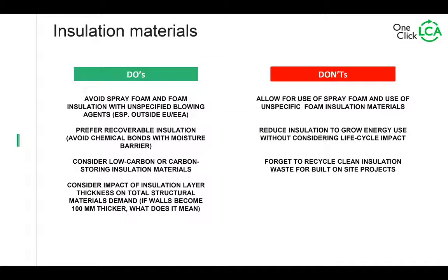The most important thing is to avoid spray foam, avoid it altogether if you can, and avoid any foam insulation with unspecified blowing agents. If you are operating inside the European Union or EEA, there are many blowing agents which are prohibited, so they cannot be used. But if you are building outside of the EU and EEA, you should not allow use of any foam insulation with unspecified blowing agents. And you should review what actually is used before you accept use of foam insulation of any kind. So just don't do it.